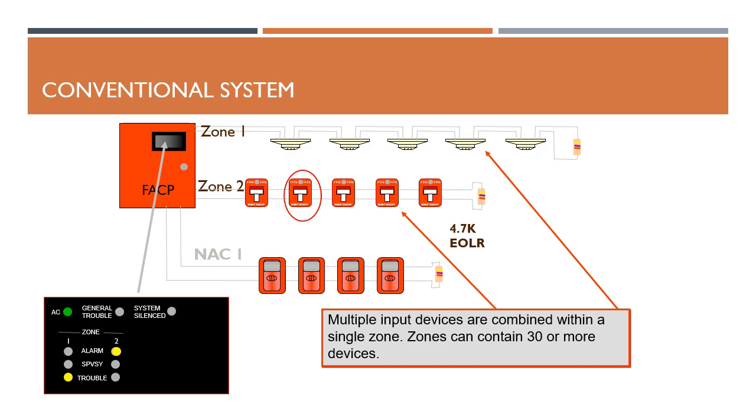Now, let's imagine that we have a problem in zone 1. In this case, somebody cut the cable between detectors 4 and 5. The panel automatically sends us a warning that is known as trouble in zone number 1. As in the previous example, we do not know at which point the cut occurred, so we will have to do a general check of the entire zone.